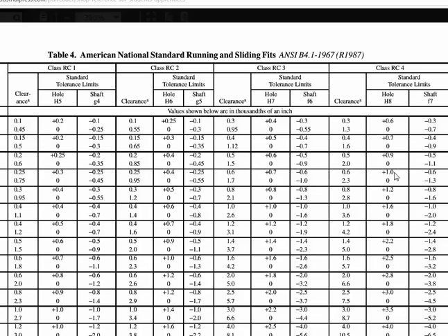Now this does not mean 1 inch wiggle. It means instead thousandths of an inch. And if you take a look right here, all these values are shown in thousandths of an inch. So that's 1 thou. That 1 thou has to be added to 625 thou, so you get 626 thou. Then over here for the comparable shaft that will create that running clearance fit, the shaft has to start with the nominal size and get smaller in order to be a clearance fit all the time. So the largest that the shaft can be is the nominal size minus 6/10 of a thousandth of an inch. Its least material condition is going to be the nominal size minus 1.3 thousandths of an inch.